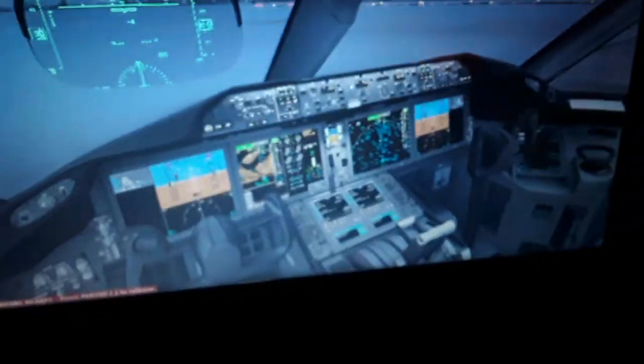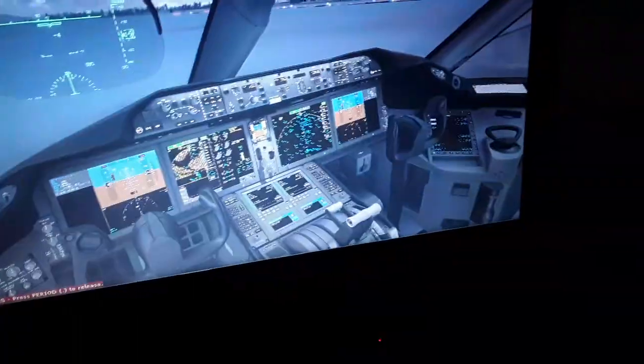So this is a fly-by-wire aircraft, the Boeing 787. It has the flight control computers to control the flight control surfaces, deflection in the air, to limit and control the maneuvers the aircraft makes in terms of G loads and acceleration of the gravity loads, in terms like 2.5 Gs, in left and right turns, so 67 degrees in the Airbus, or 30 degrees or 1.5 G incline, and minus 15 degrees or minus half G in descent. This is the Airbus limit. I'm not sure about the Boeing limits, but it must be similar because this is how the fly-by-wire acts.